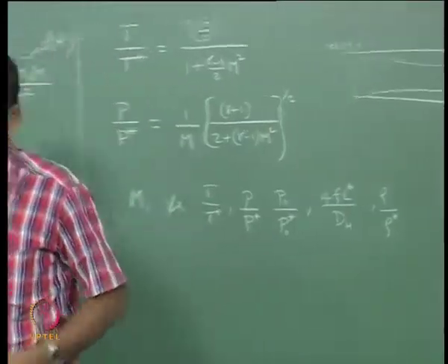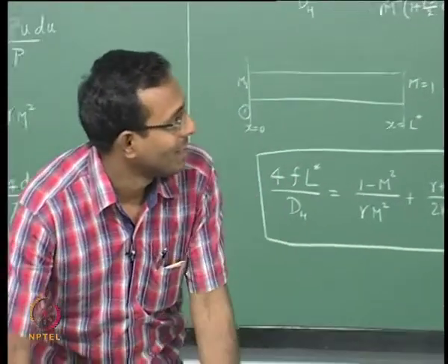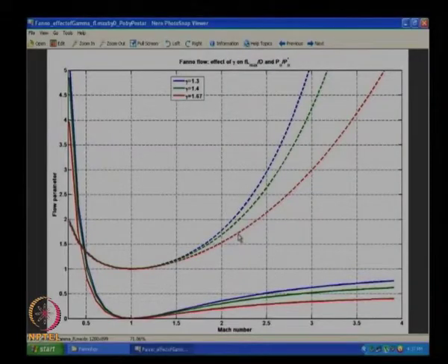Now, we will go back to the remaining plots we have. If I think about the compressible case, for the same Mach number, the P naught drop is a lot higher in supersonic condition compared to the less compressible case. If it is more compressible, the energy drop, P naught, is much higher.